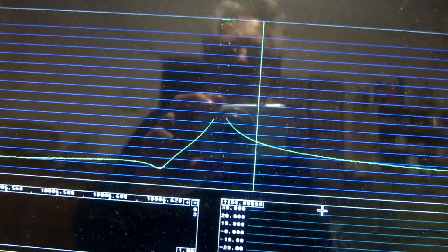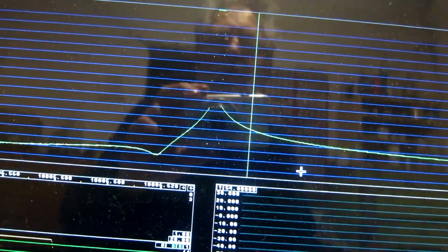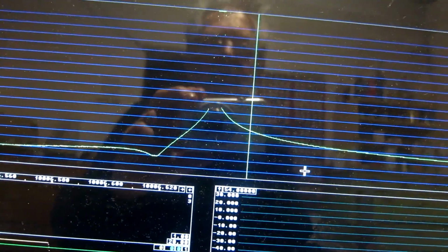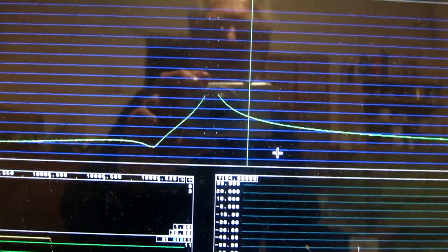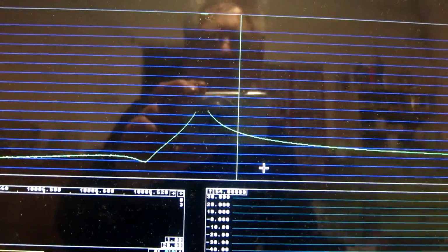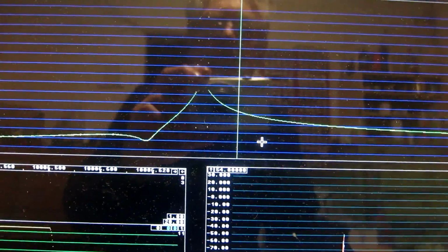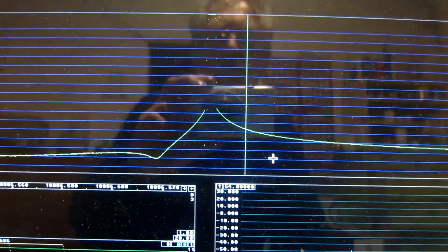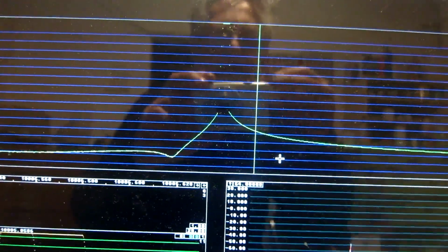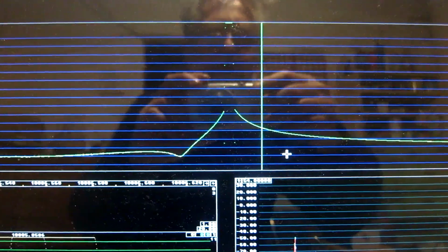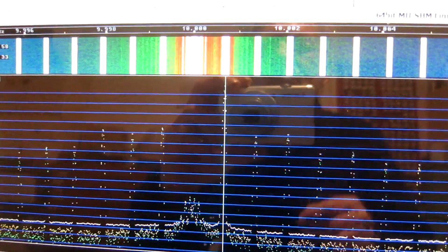And this doesn't look right. I will look into it a little bit better. Seems to be an error in the window function. Probably it doesn't start close enough to 0, so there is a discontinuity when the window starts. I think the criterion was -180 decibels when I set up the window originally.